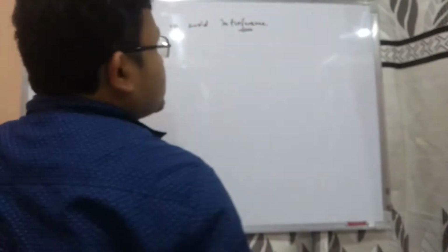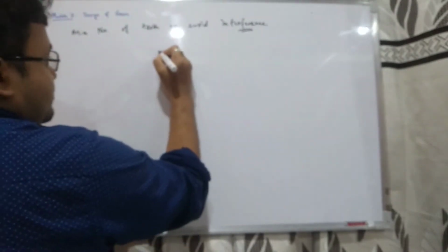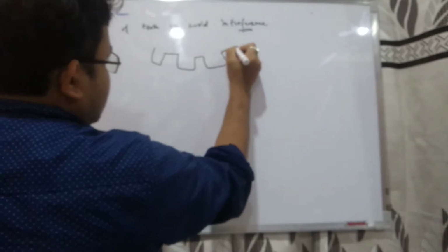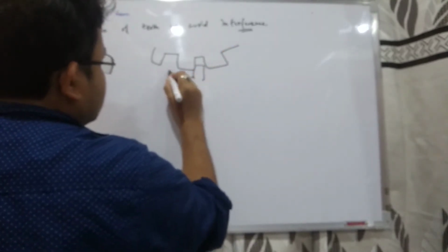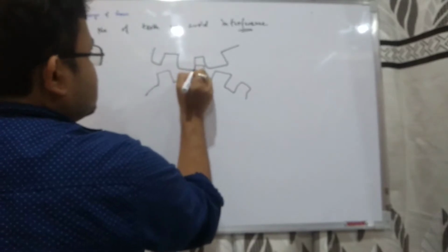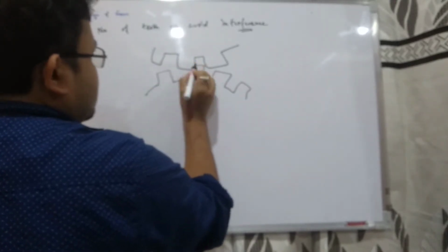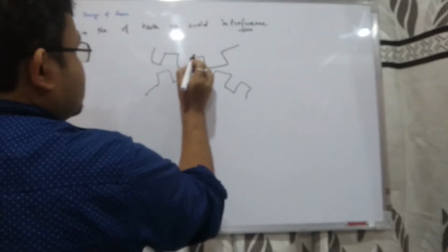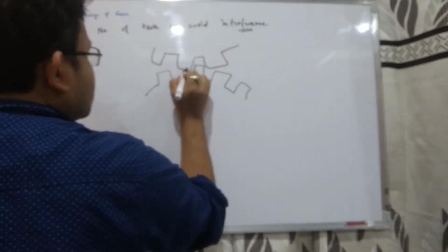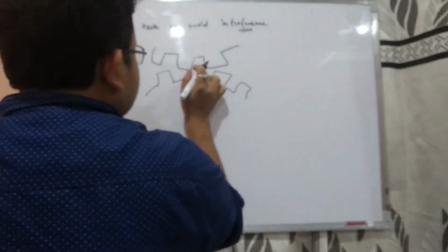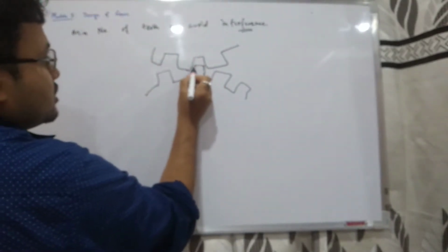Although you have studied it, interference is a phenomenon when we see two gears meshing with each other like this, and the pair of teeth clash with each other. That means due to a problem in their involute profile, this gear will dig into this one.